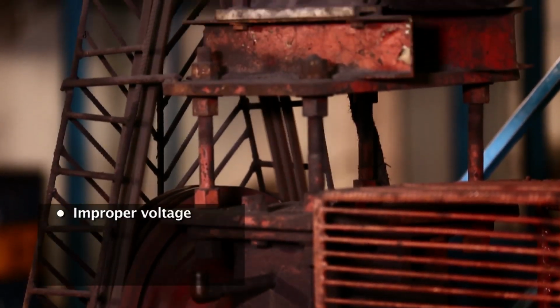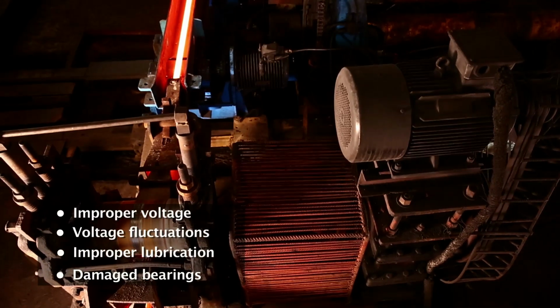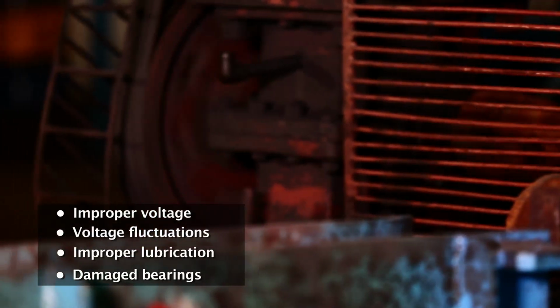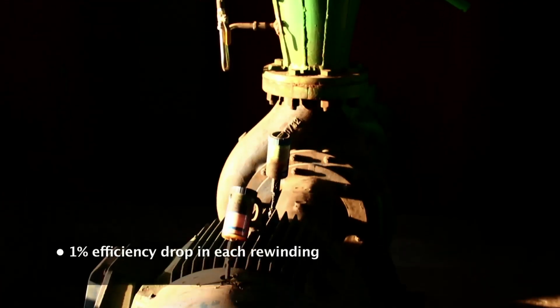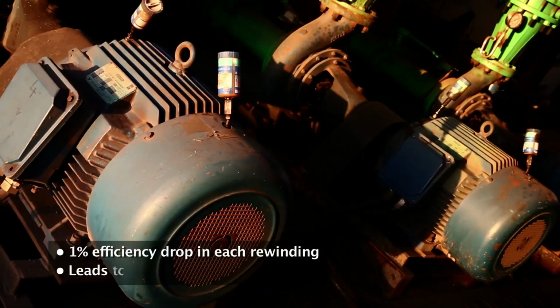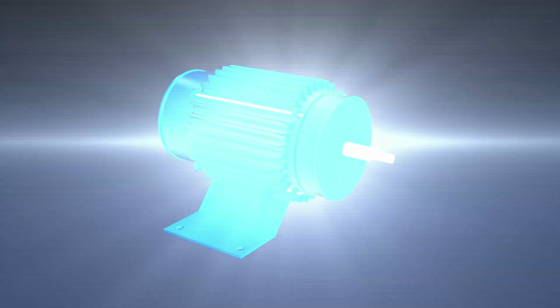Often, improper voltage fluctuations, improper lubrication and damaged bearings lead to a rise in motor winding temperature, ultimately leading to failure. These electrical failures lead to the next obvious step, motor rewinding. Considering a 1% efficiency drop in each rewinding campaign, it may lead to a loss of 45,000 rupees per kilowatt hour.